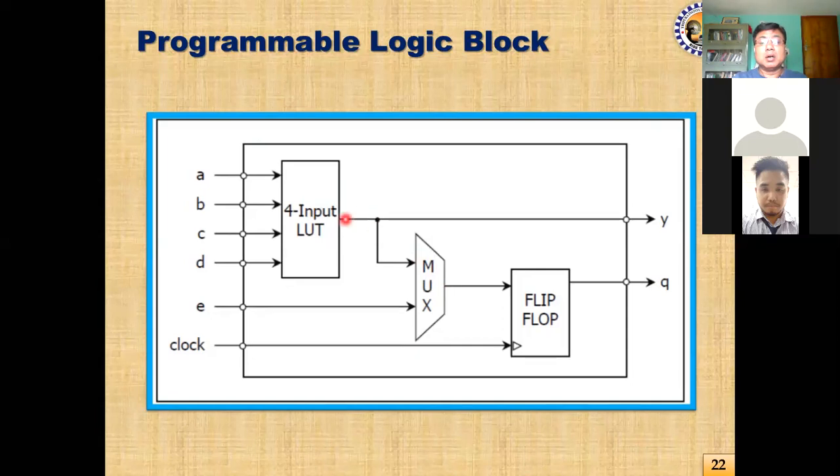So if your expression is combinational, you implement that circuit over here, and the combinational output is available here. Inside this block, since this flip-flop is there, this flip-flop will not be used. So the designer, in order to optimize the use of the resources available inside the FPGAs or logic blocks, has kept an extra provision.